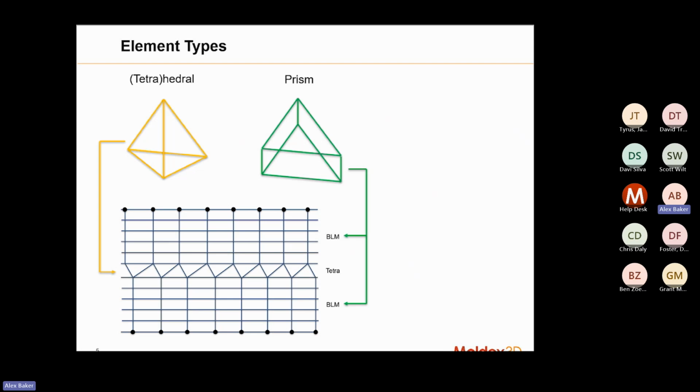But they do actually kind of fall flat in any sort of high deformation analysis. In molding analysis, it's fine because it's pretty low deformation. But once we start getting out of that linear elastic range, these prism elements end up being poor quality, whereas they are extremely high quality for flow analysis. We use them in Moldex3D, but when you get over into your structural analysis, you'll want to use something more like a tetrahedral element that's a little bit more flexible.